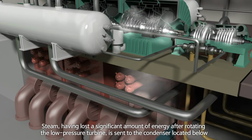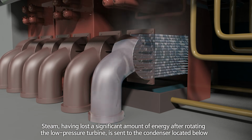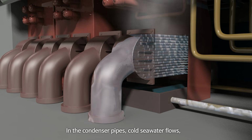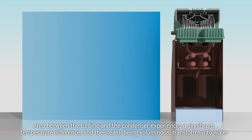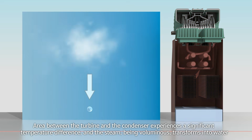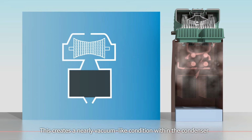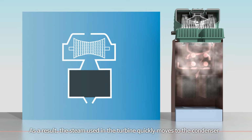Steam, having lost a significant amount of energy after rotating the low-pressure turbine, is sent to the condenser located below. In the condenser pipes, cold seawater flows, causing the steam to lose heat and condense back into water. The area between the turbine and the condenser experiences a significant temperature difference, and the steam, being voluminous, transforms into water. This creates a nearly vacuum-like condition within the condenser. As a result, the steam used in the turbine quickly moves to the condenser.